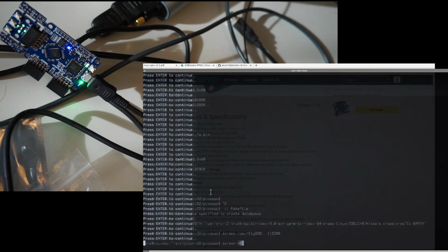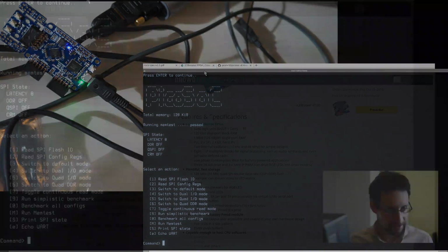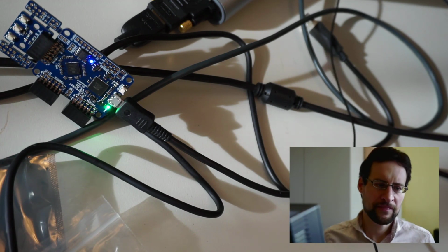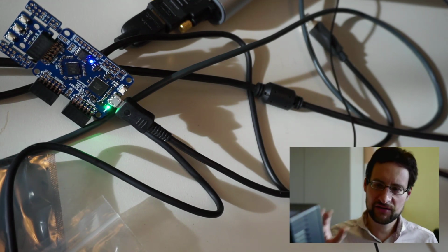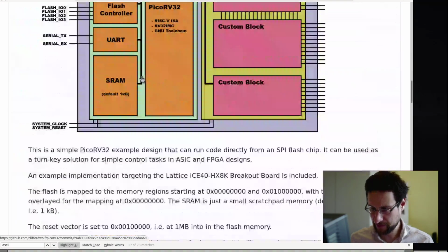Also reattach here. And yeah, here's also the memory. And this will be quite challenging actually: to integrate the HDMI output, we need to design a small FPGA character generating video graphic adapter thing, and connect this to the bus of the Pico RISC-V.